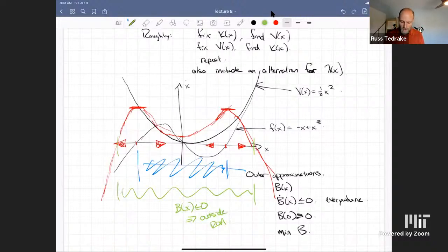The thing that's magical about this is that we can do control design in a convex way. If I were to put in control design, you see there's no multipliers there that multiply lambda. There's no lambda of x times v of x or anything hiding here.